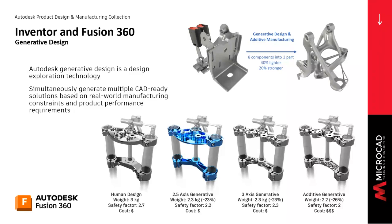The study setup not only accommodates material, so we actually set up the generative study. We're going to specify what different types of materials that we want to use. What are the safety factors? What are the concerns? And what are the potential costs? And also based on the manufacturing method. Am I going to do conventional machining or am I going to do additive, if I have the ability for that kind of technology?